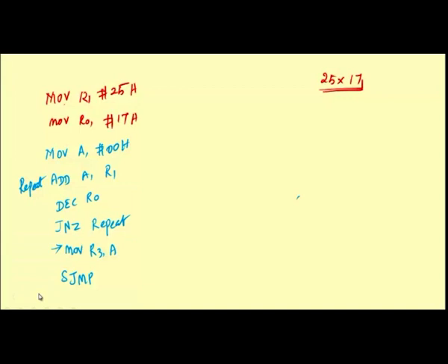What does it represent? Instead of these two, you can use decrease and jump. Here we are using the decrease instruction, then the jump instruction. Instead of that, you can use DJNZ, decrease jump not equal to 0. Then you have to give the register, then the label. So, by this also you can use it. Okay. So, this is one of the instructions, decrease jump not equal to.